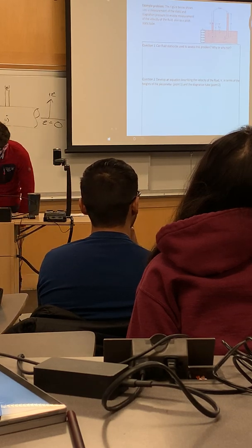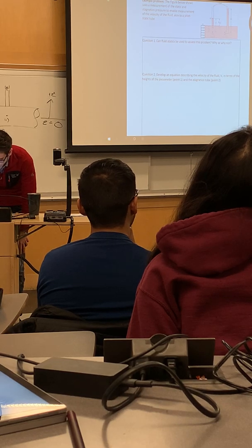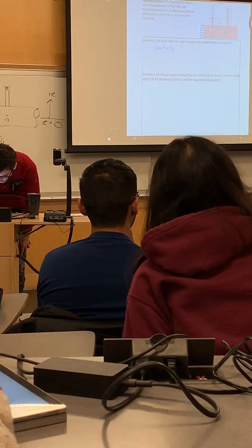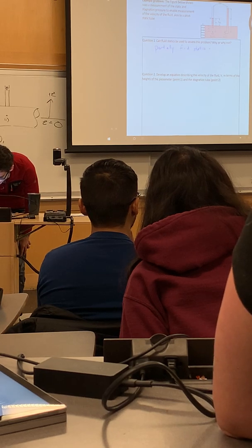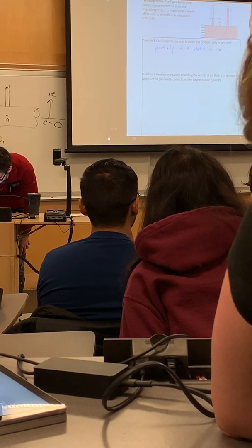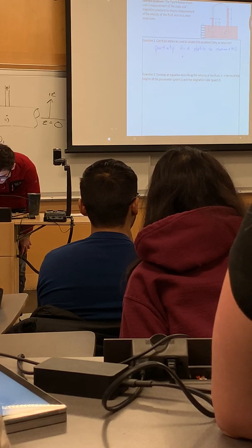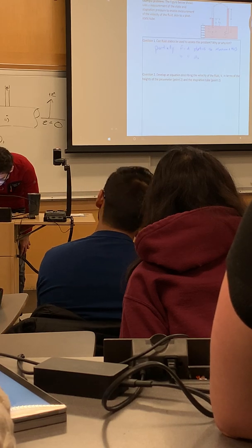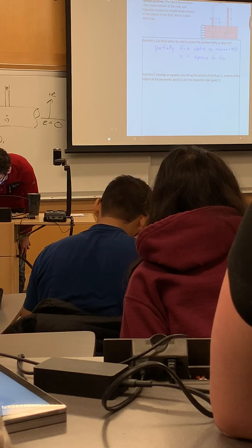So, again, we already talked through this. Can fluid statics be used to assess this problem? Why or why not? This is sort of an in-between answer. It's partially, right? So we can apply fluid statics to the manometers, but we need fluid dynamics for the flowing tube.